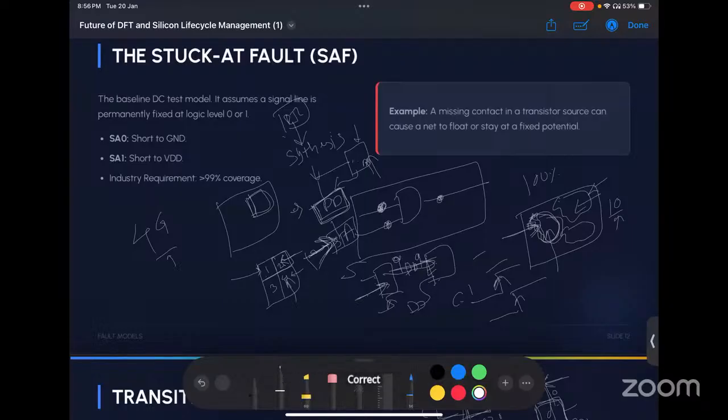So what you need to do is delay this clock a little bit, to make sure there's a proper launch and capture: launch from this one and capture from the second clock. So we delay this clock a little, so that it comes at this point, and before the next edge, this edge will capture the data.